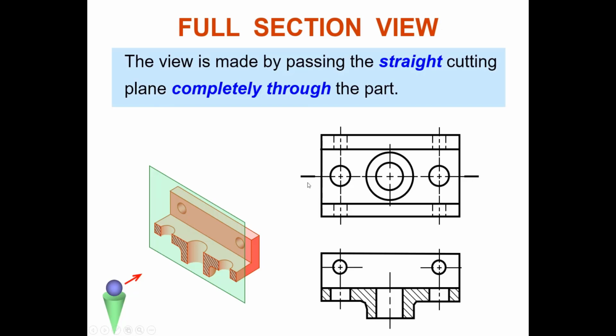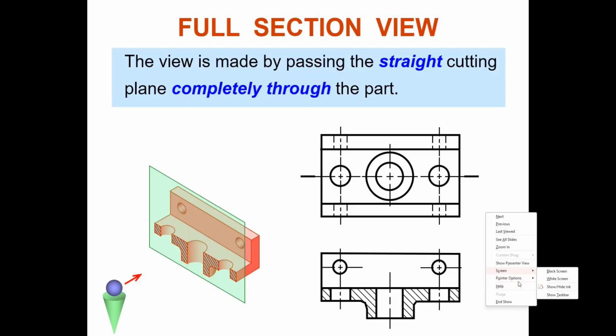In the terminology, you also have to memorize this. This is what we call section lines. At both ends it is a little bit thicker. So it means that at the front view you have the section view. Can you see? Okay, take note here, your section view.